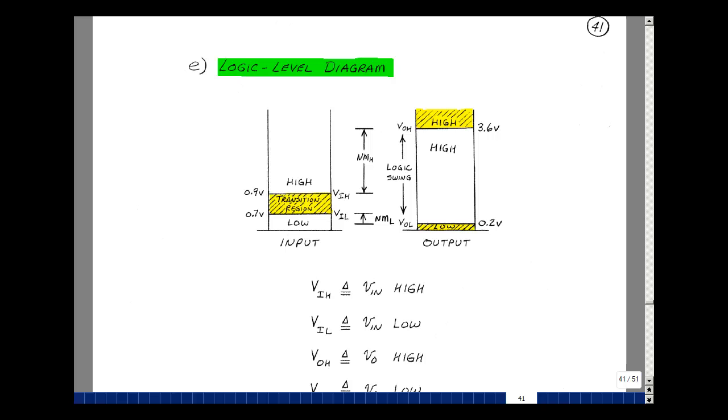There are many different technologies for implementing a logic gate. We need some way to compare them. One way to do that is with a logic level diagram. Let me explain the following. For an inverter, we had an input such that whenever we were below that value, the output would change state. We're going to call that V input low. Then we also had calculated a V input high, such that whenever we were greater than or equal to that number, the output changed state. We had calculated 0.7 for V in low and 0.724 for V in high, but the manufacturer suggests using 0.9 for the input high. This is because the values of beta F, VBE on, and VCE sat vary as you manufacture transistors.